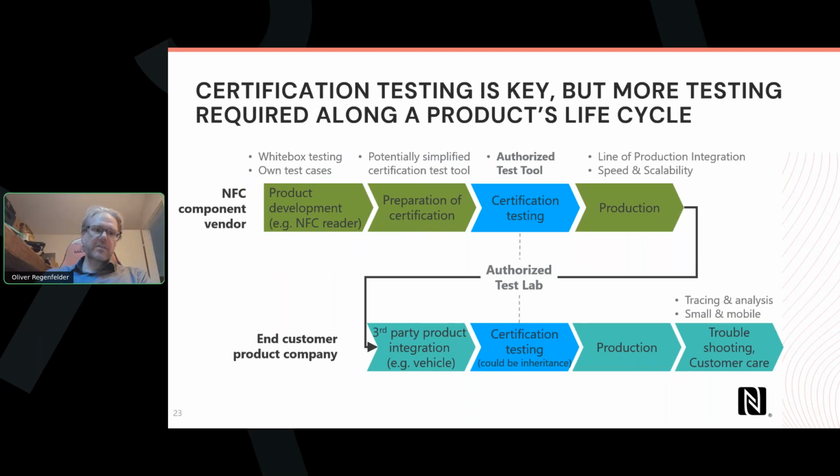Then in the next step, an NFC component vendor will often prepare a certification of his own. So for many components, you will get demo boards which have been already certified, so that you can rest assured that they already comply to the specifications. And once that is done, an actual certification testing at an authorized test lab with an authorized test tool takes place.